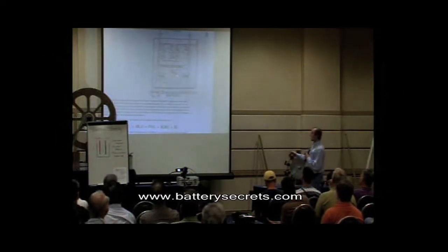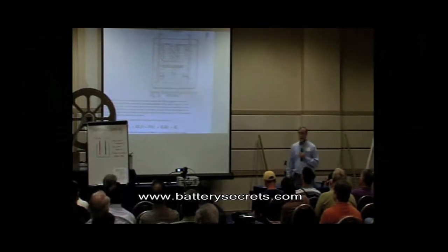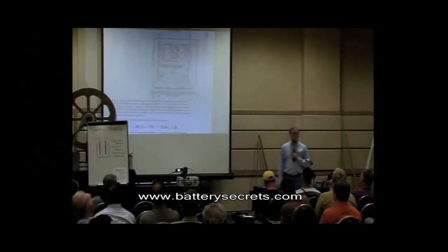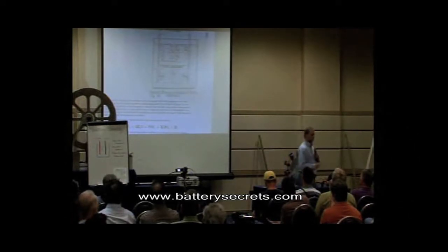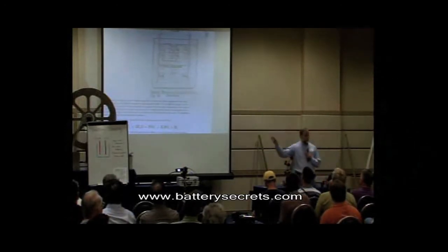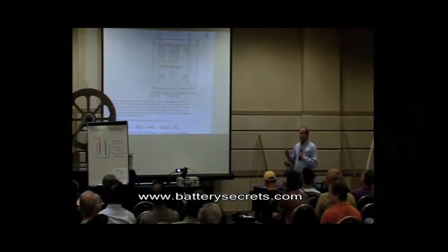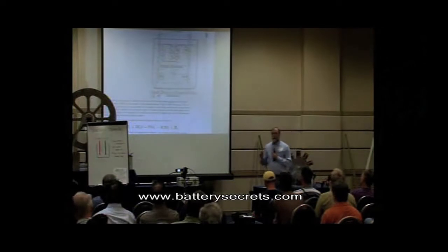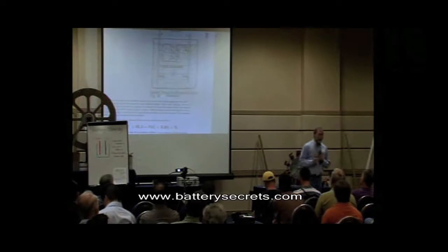And we need that oxygen to go back over here and chemically combine with the lead to produce lead oxide and plate out on the positive plate. We need to be able to destroy a water molecule, the one we created when the electricity was made in the first place, and do it in such a way that it causes a chemical change in the battery.